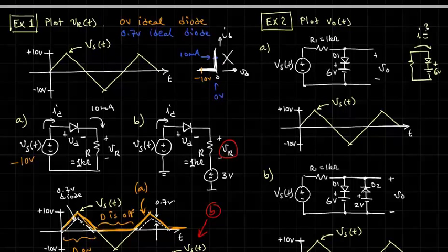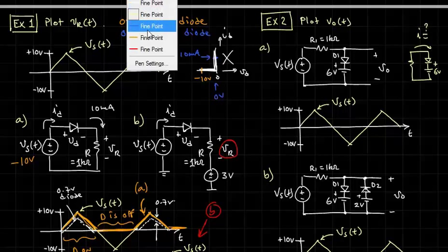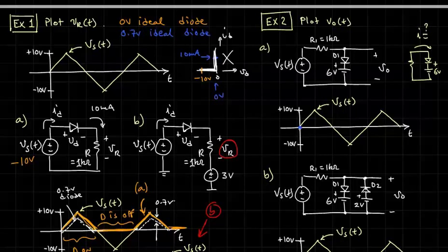If it weren't for that diode, we'd actually have a current I equal to minus 6 volts over 1K. But the diode prevents it. So when you have Vs equal to 0, D1 must be off. So I'm going to plot that point. Because if D1 is off and Vs is equal to 0, then clearly the output voltage is just Vs because there's no current flowing through R1.